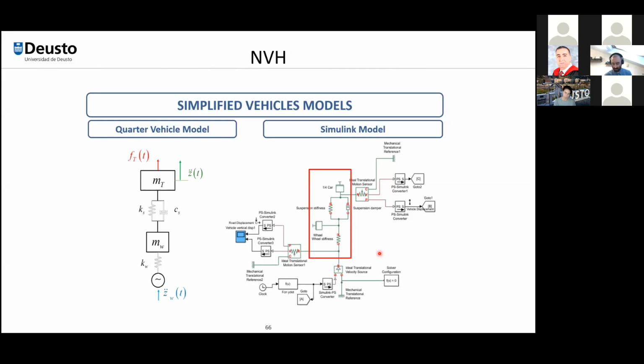The last question is about the critical value of damping. As you know, in general, with a driver and passengers, the mass of the vehicle varies as the number of passengers increases. In this case, the damping ratio will change also. The system may transfer from an over-damped system to a critically damped system to an under-damped system. What about the analysis of the vibration dose value compared with the damping ratio of the vehicle, or the dynamical system of the vehicle?